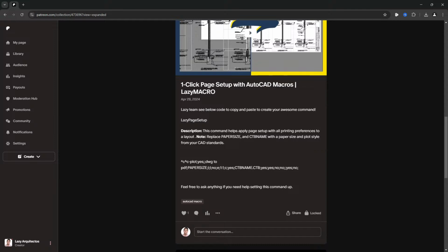So again, Altamash, you may be facing the problem of picking a size A1. Maybe you don't have that A1 in your system, so just check before that it exists in your drawing, that it matches exactly the name of the sheet, A1. Maybe there's a point, maybe there is a dash, A-1 or something like that.